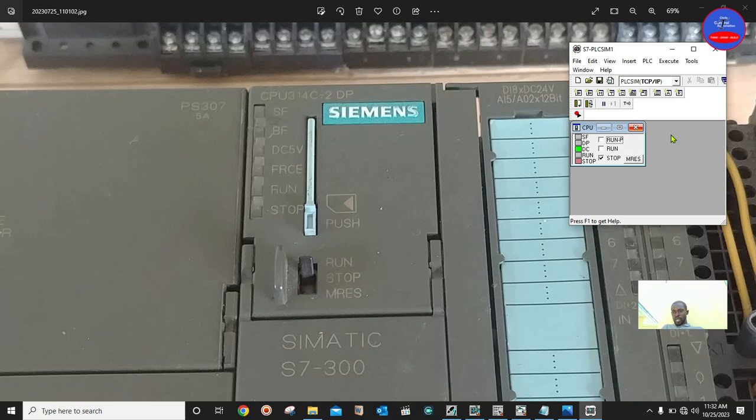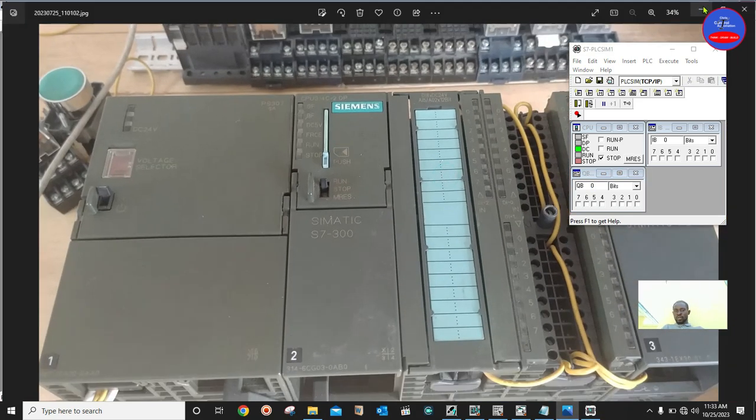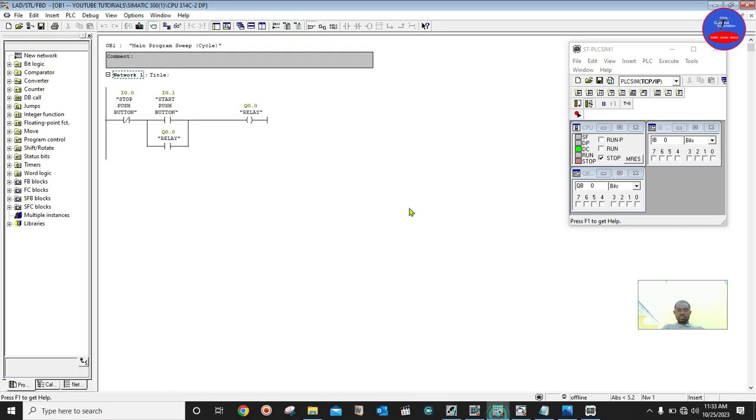Now I'm going to show you how to create a new input and output byte. You come to this side. You see this first icon? It is written: Insert input variable. So you click on it. It is here, right? Then Insert output variable. You click on it, and it's also here. Okay. So now we are going to download the program onto the PLC using this communication protocol.